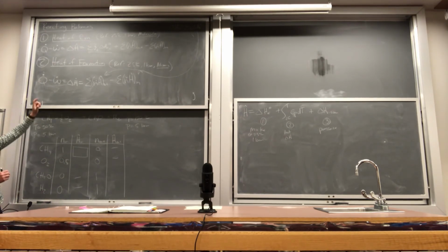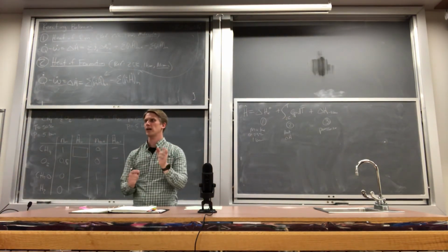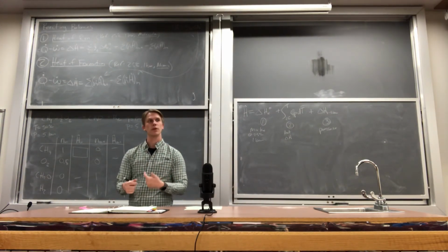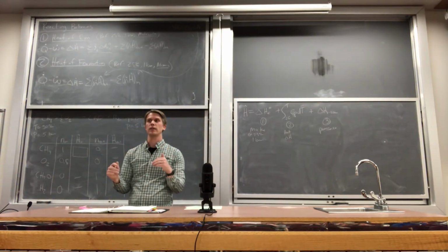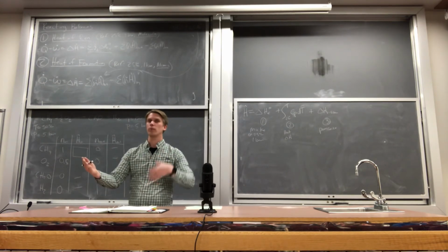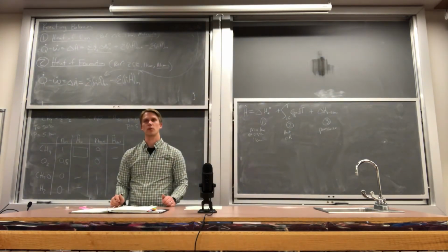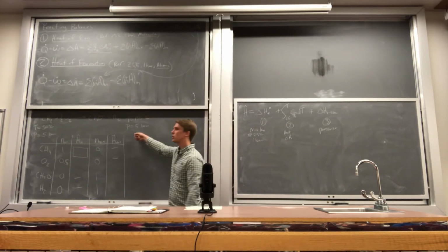So it's important to recognize that in the heat of reaction approach, you're actually forced to go through and think about how the different reactions contribute, or how they might change as a function of temperature. So there is value in looking at what the different heats of reaction are and how they change as a function of temperature or process conditions. Because if you have one endothermic and one exothermic, you're going to be promoting one or the other if you're changing the temperature of the reactor. In the heat of formation, we don't care.